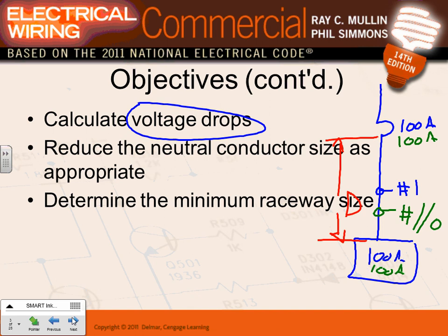If it's not, what do you need to do? Oops, go up one size. That's why, Aaron, when you go to engineering firms, you're going to find that they go to 100 amp, they always go higher than the conductor from the get-go. A lot of engineering firms go, if the size is 1, we'll go higher, right? We'll jump into the next size from the get-go without messing around because of what? Voltage drop. Voltage drop. Can I have thumbs up, Chad? Because of that voltage drop.